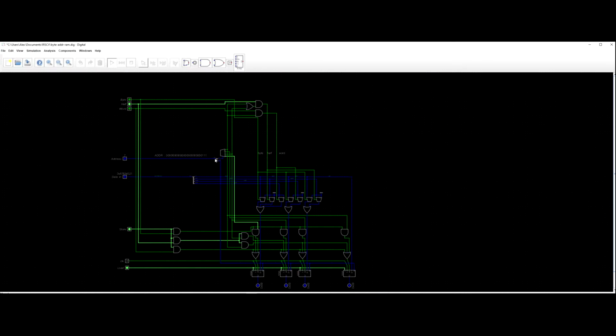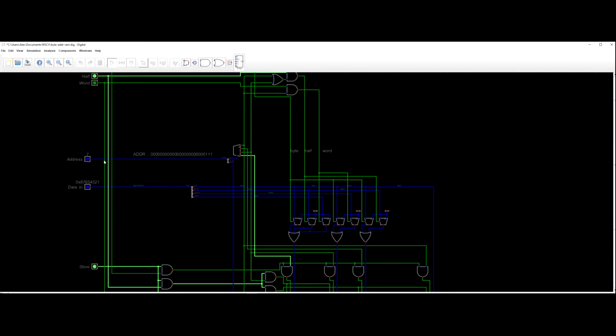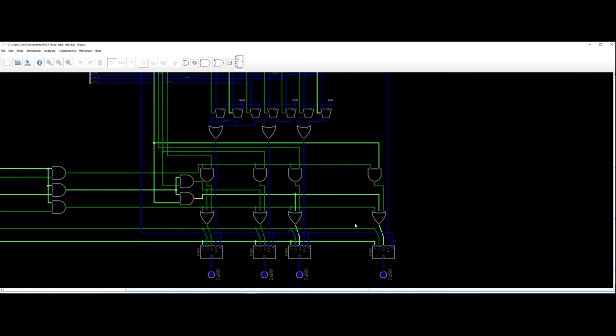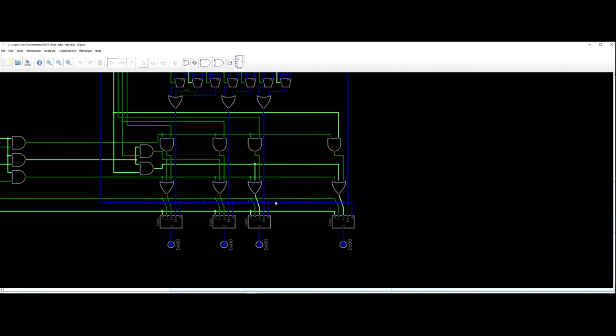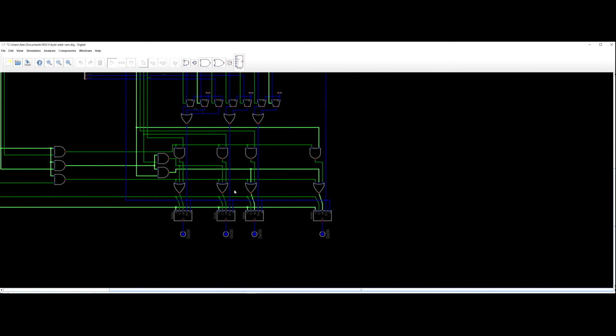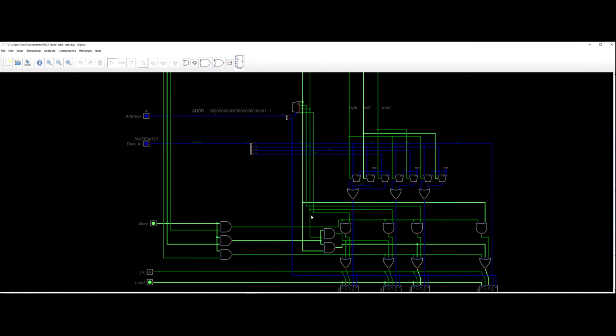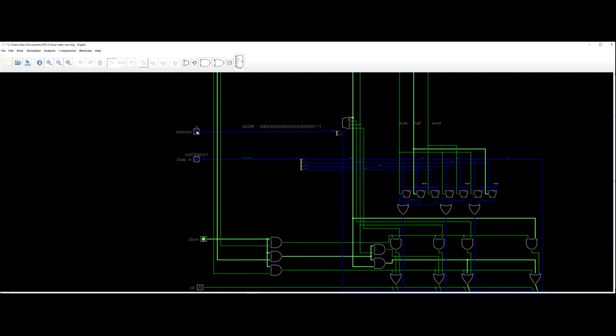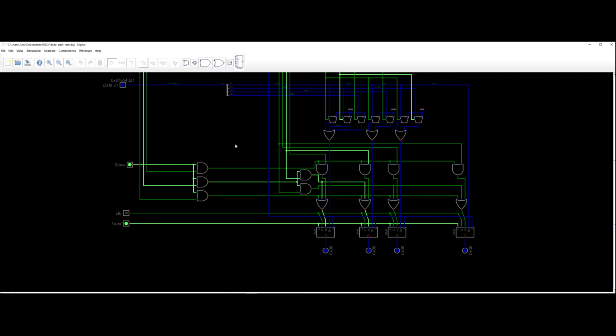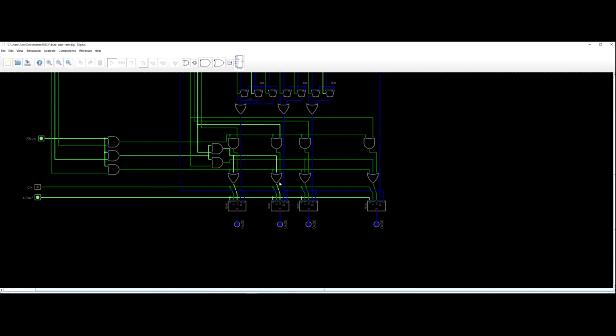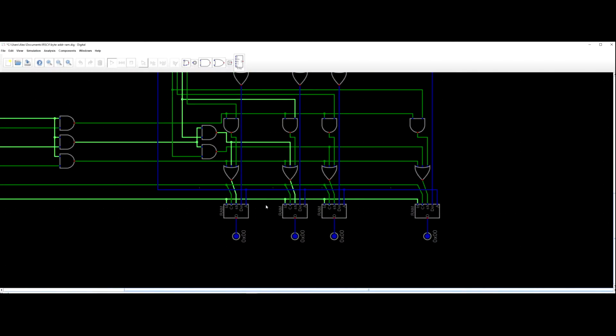But if I align my address here, the last two bits on 0, 0, apply, you'll see that now I'm able to store, and the two that are going to store are here and here. Now this one should get 21, and this one should get 43. Nice. Okay, now the other way for this to happen is instead of address 4, where that's 0, 0, we make that 1, 0, 6, and now it should be storing to these two, which it is.